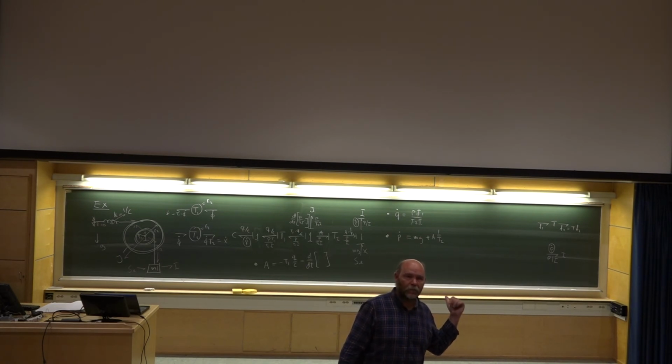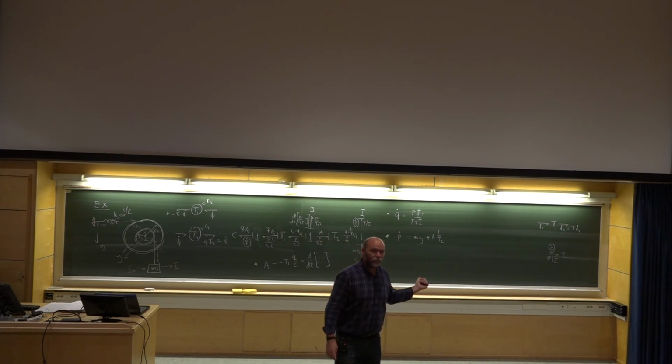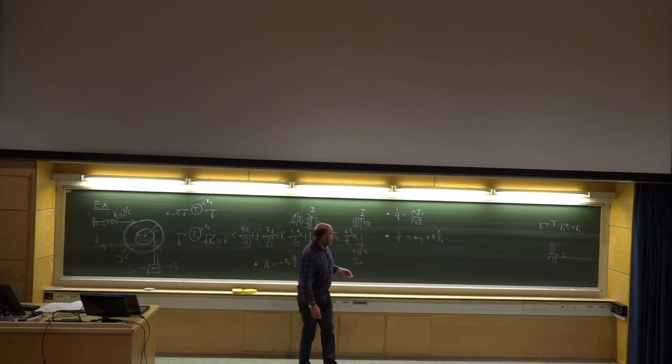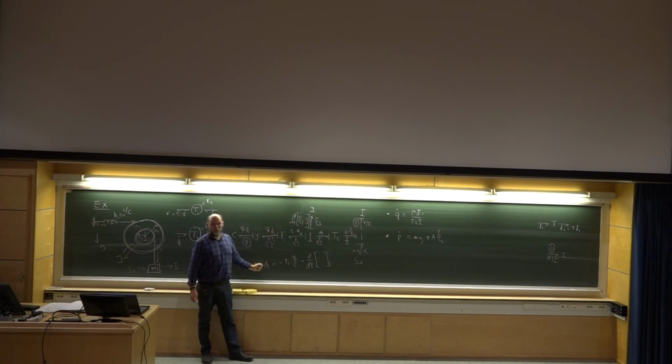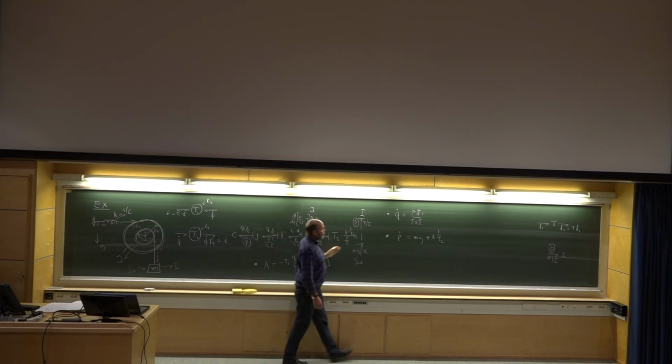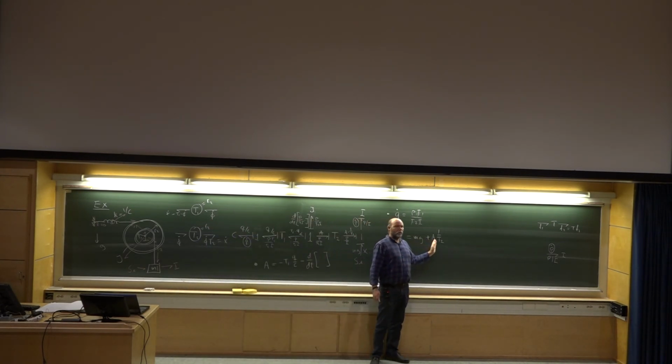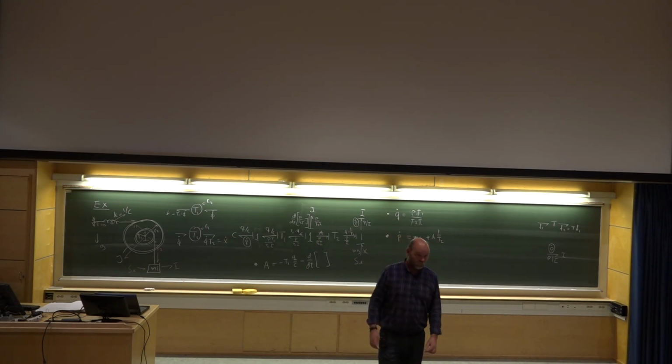You don't have to do this algebra. Calculate A first and just use it. MATLAB has no problem with fighting with what you call here a DAE system. It's differential and algebraic equations at the same time. So in the same function, you just calculate this coefficient A first, this parameter, and use it in the expression later on. No problem. So don't do all the algebra unless you have to.